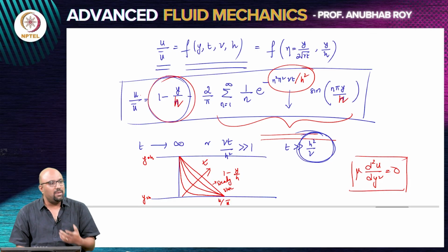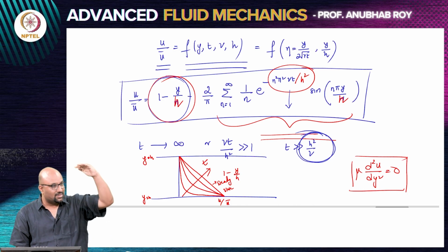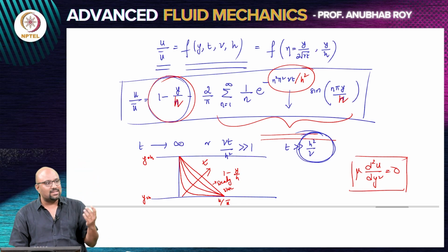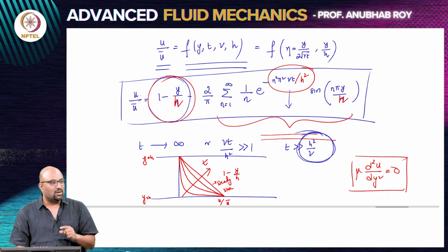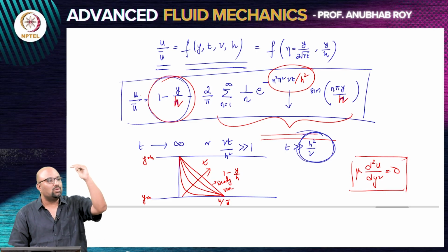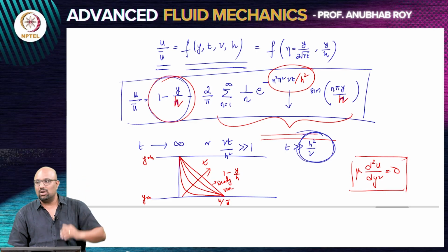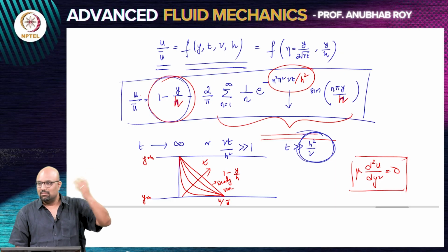But you will not be able to achieve this solution if you disregard viscosity. You can see this now: when you move one boundary and hold the other one fixed, we all know that you are going to get this linear plane Couette profile. But to achieve it, you need viscosity, because you will have momentum gradually diffusing from the bottom boundary to closer to the top boundary, or whichever is differentially moving.